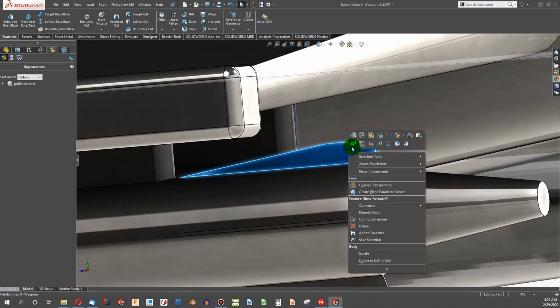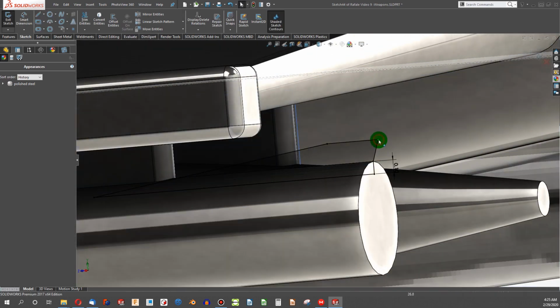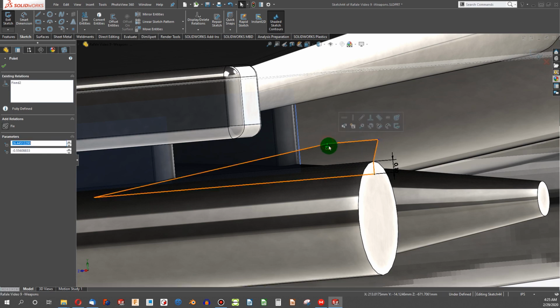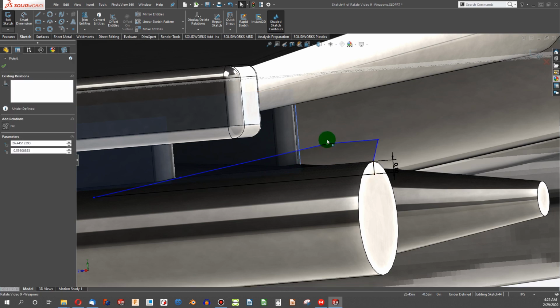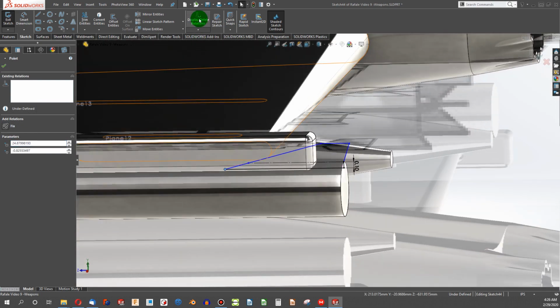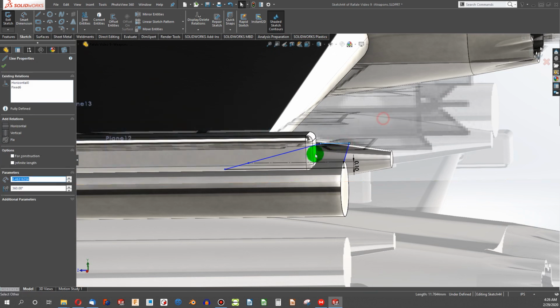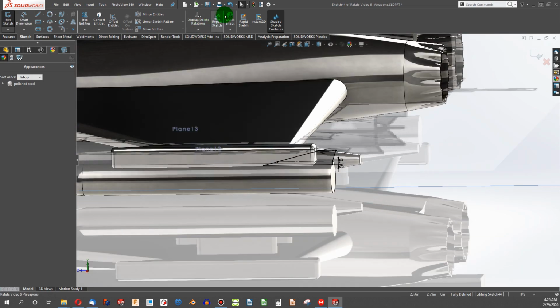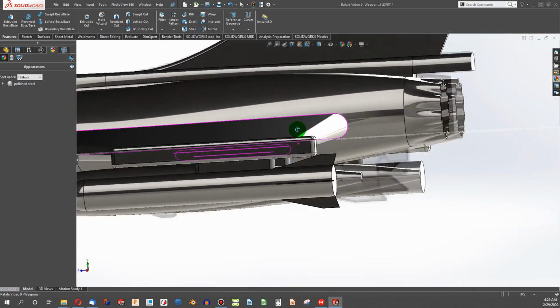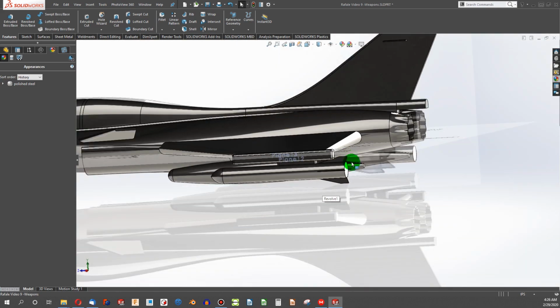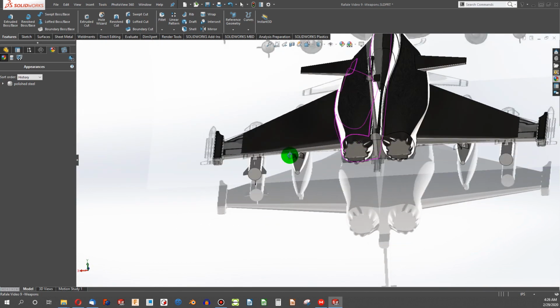So of course, if we wish to alter fixed geometry, the way to do it is to make sure that everything that you want to alter is in blue, and I want to alter that angle, so that's a bit more like it. You'll notice we'll reduce this distance so we don't interfere with where the missile is mounted, and you can either refix it or leave it be. And rebuild. Here's our fins, and we're not interfering there. Okay, we're going to say that that's pretty good.